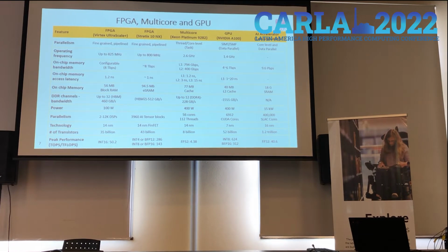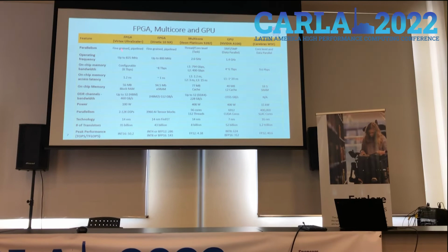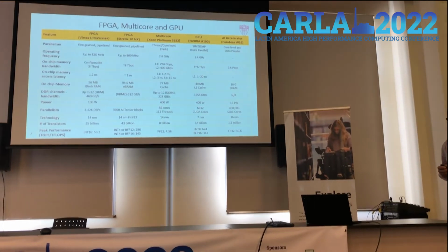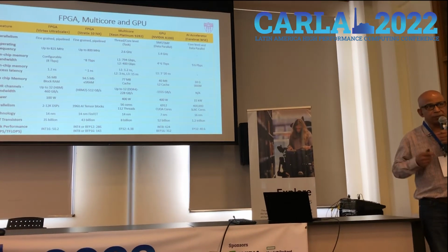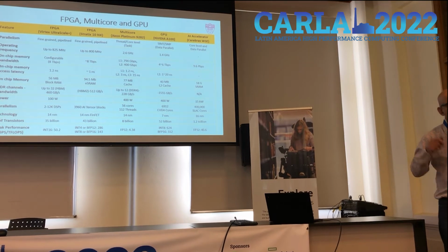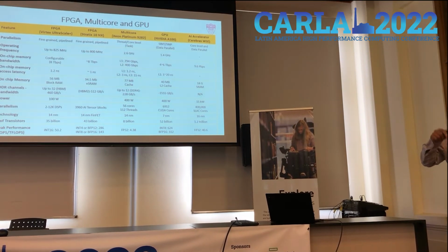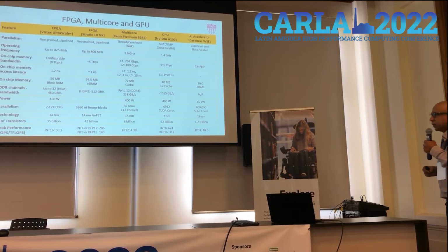But keep in mind that these architectures are not like the programmable architectures here. You have to actually devise the complete virtual overlay architecture on top of this FPGA device, so that you have full control over what architecture you want to implement, and that architecture is the one that will execute your GNN training.